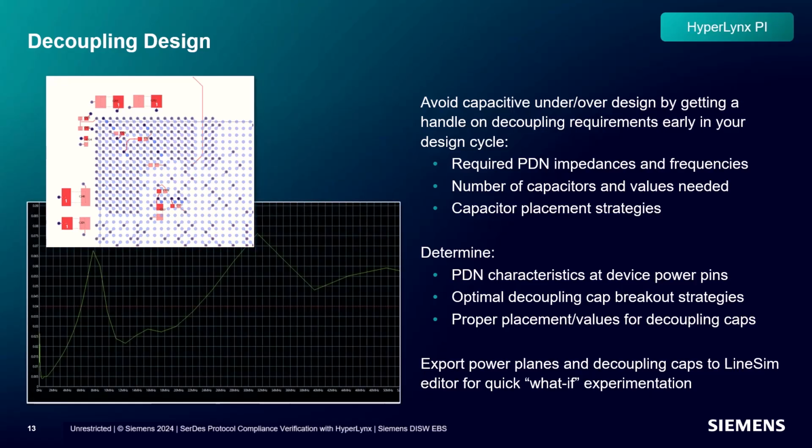The observed AC noise will vary with frequency, depending on the decoupling capacitors used, their quantity and location, and how they are connected to their respective power planes. PDN impedance is a complex, distributed problem best suited to analysis with electromagnetic solvers.